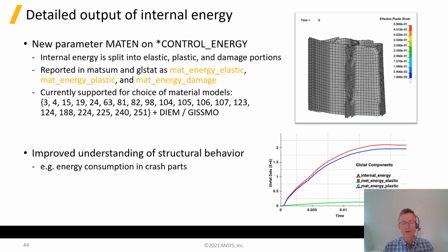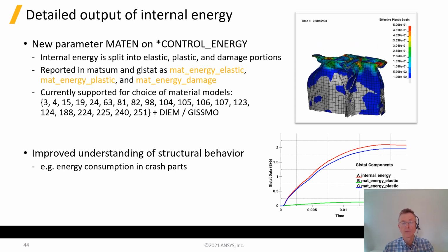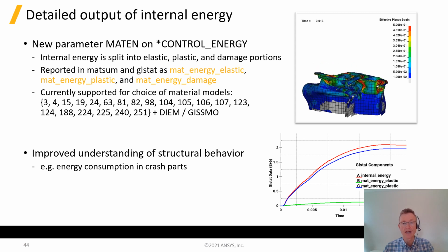And if you're trying to track down where the internal energy is being spent in a certain part, you've now got an option to split the output energy into elastic, plastic, and damage, which is supported for the list of material models shown on the screen.